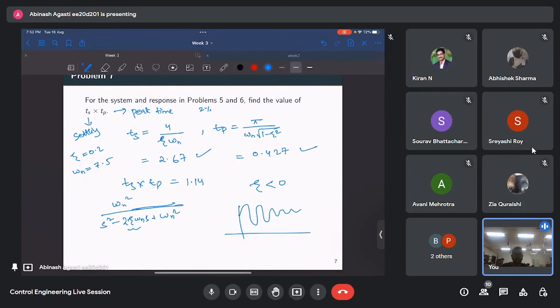And on the other hand, if I have negative damping, what that means is any oscillations that I have will keep growing, they will go unbounded. But in most of your physical second order systems, I don't think you'll have negative damping, because damping is usually things like resistance or friction and stuff like that. So the damping term in any real world case for a simple linear second order system will not be negative, but theoretically, or by manipulating things, we can construct a second order system which will have an equation of this form.